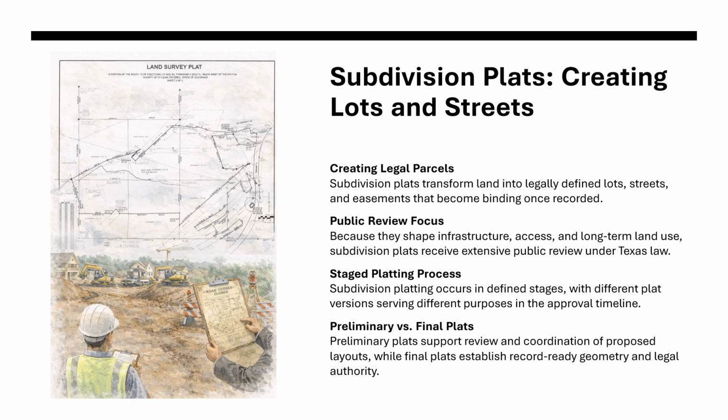The reason subdivision plats receive so much attention is not because they're complicated drawings, but because of what they represent. A subdivision plat does not simply describe land. It creates new legal parcels. It establishes streets, and it dedicates easements that the public and future owners will rely on. Once approved and recorded, those decisions become binding. They shape infrastructure, access, drainage, and long-term land use in ways that are difficult or impossible to reverse later.